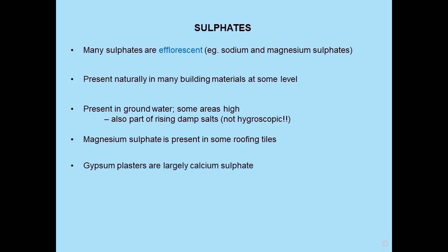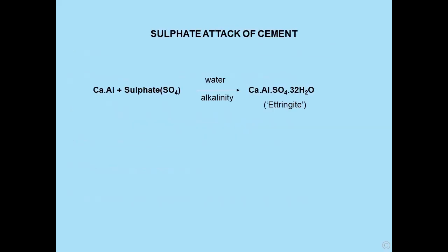Gypsum plasters are largely calcium sulfate, and they can cause sulfate attack in newly applied cement renders and plasters. So, have a look at sulfate attack of cement. Cement is incredibly complex, and the chemistry of cement is also incredibly complex. So let's just simplify it for our purpose.